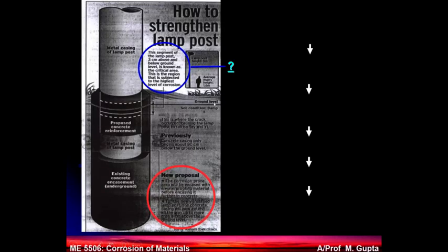Now if you see this picture here, for example, here is a lamppost. If you follow the cursor here, and here are all the lights, it's not very aligned, so you will not have a vertical load but an inclined load. So the crack under the application of the load will not be under compressive load, it will be some kind of shear load happening in there, and that leads to the ultimate failure.